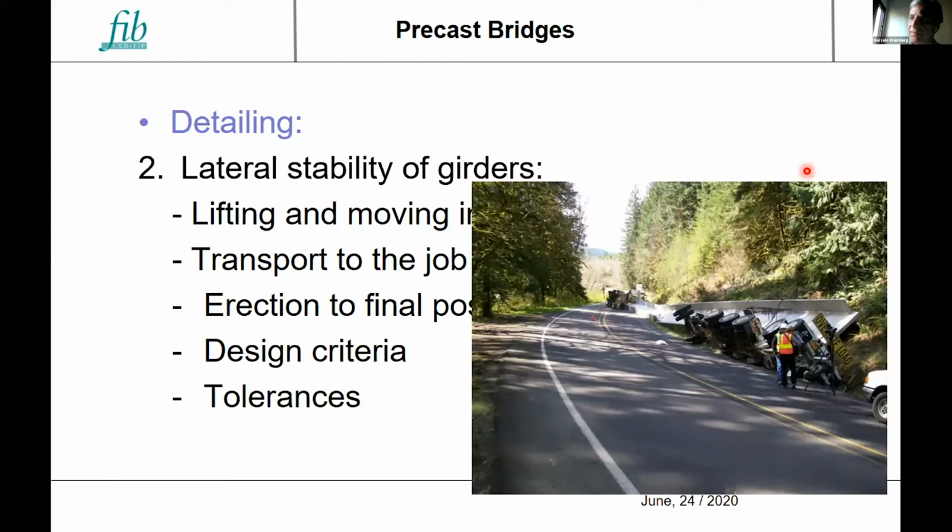And what I think is a very useful tool: the report will also contain a spreadsheet that you can use for all your checks, just by inputting your local data, such as codes, tolerances, the geometry of the girder you are designing, and the condition in which in your country you usually move these girders along roadways.